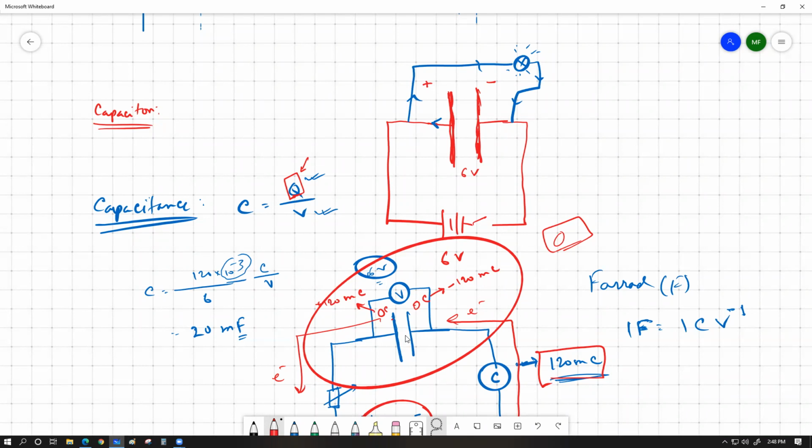To the question you asked, whether energy will be stored in only one plate, the answer is no. Pretty much like a battery, a capacitor also works in the same manner, that it will always have equal and opposite amount of charge stored on its two plates. This is always true. Even if one side is connected to earth, grounded, this is still true. Why true?